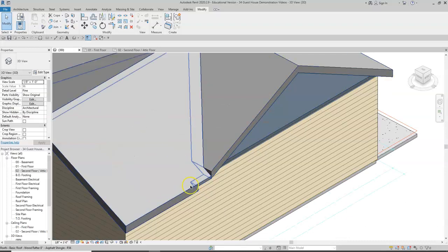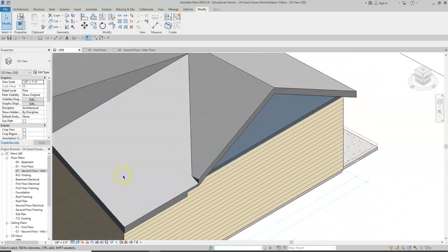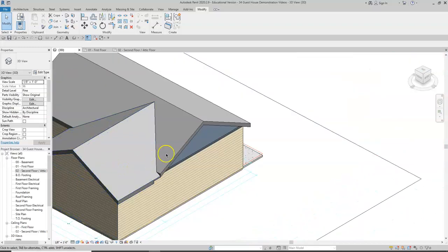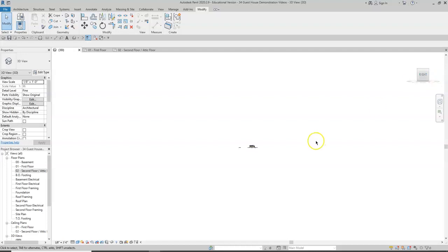Now notice we have an issue here where the overhang, the height of the roof is different for the 6/12 on the front end and the 6/12 on the back end. That's because the actual distance of the span of the roof is different. So to fix this issue, we will go to the right hand side of the house.